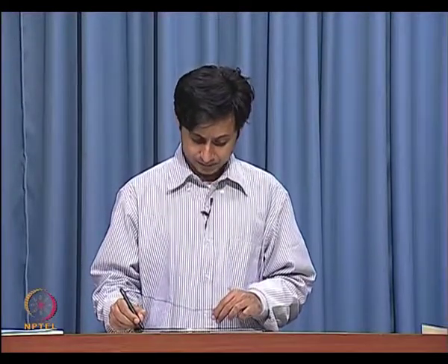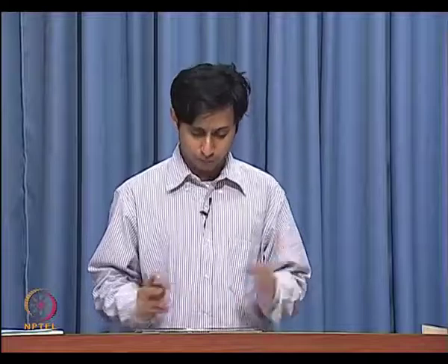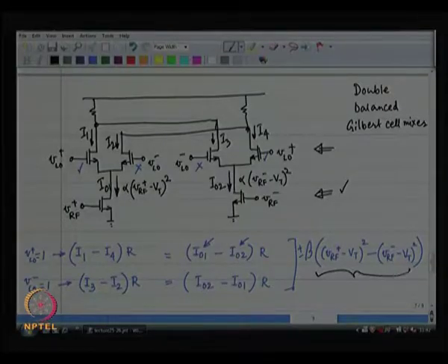because there are now 4, you have to drive 2 sets of transistors, all right. So, that is why we wanted to bring the RF to the bottom layer of transistors, the LO to the top layer of transistors, and this also works fine. The LO is a large signal that goes on and off, and I get this as my output. When the LO is high, I get the plus symbol over here, and LO is low, I get the minus symbol over here, all that is fine.